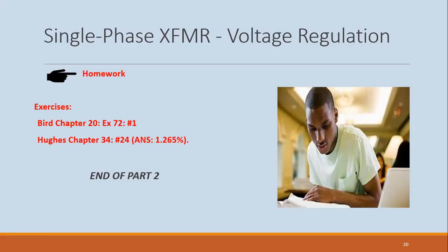Sir, question about that. When we do the open delta, are we supposed to change the shape of the delta? How do you mean? Back from slide 1, you said that when it was just two, the angle between them is 90. No, it was still a 3-phase system. The only thing we did was take one phase out of the load. It doesn't affect the shape or the angles between them. Remember, the supply voltage is what gives you those angles, the voltage, not the impedance.